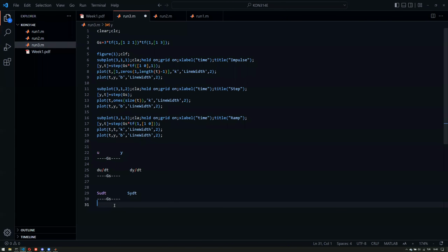So this is an interesting thing. Therefore, I know that the impulse is the derivative of step, and step is the derivative of ramp. I can just include the derivative into the transfer function, so it turns into an impulse response, because I have used the derivative of the input, so the output will also be differentiated. The same goes for the integral. If I include an integrator to the input, that also will take the integral of the output. Therefore, I can use it for ramp responses.